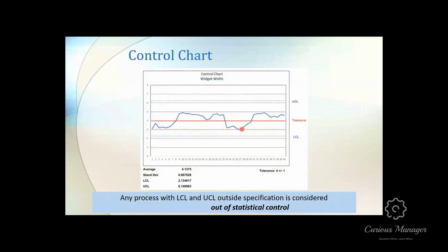All this is going to tell you is how the process performs within your upper control limit, your lower control limit, and your specification limits. If you just focused on the performance within specifications, you'd think, oh, everything's fine, everything's great. But this graph is telling me that the system is out of statistical control. You cannot safely predict that all of these will be maintained within the specification limits, not without extra help.